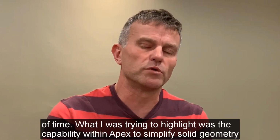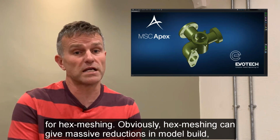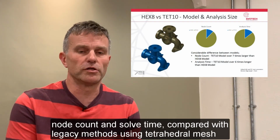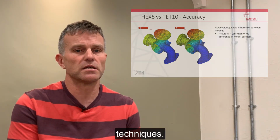What I was trying to highlight was the capability within Apex to simplify solid geometry for hex meshing. Obviously, hex meshing can give massive reduction in terms of model build or node count and solve time compared with legacy methods, maybe using tetrahedral mesh techniques.